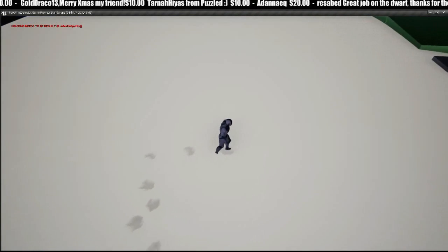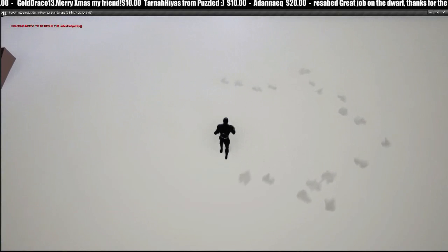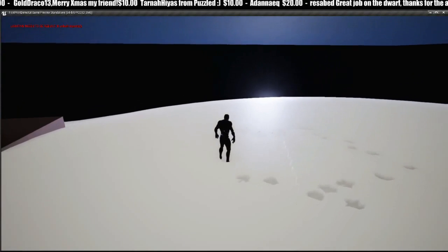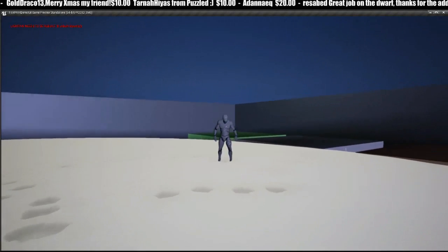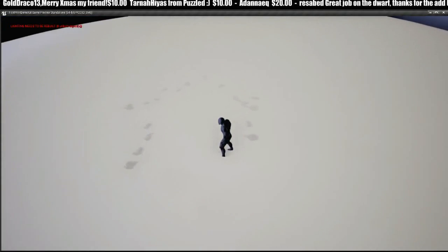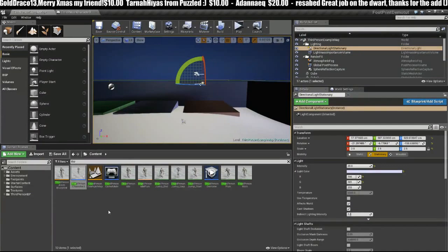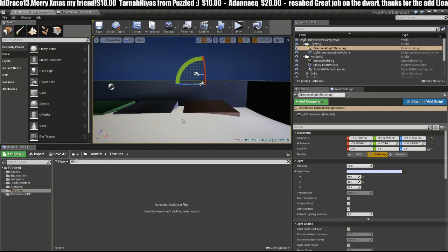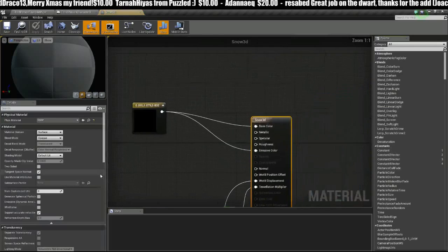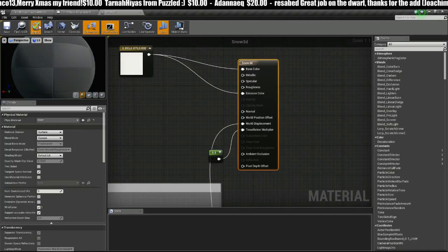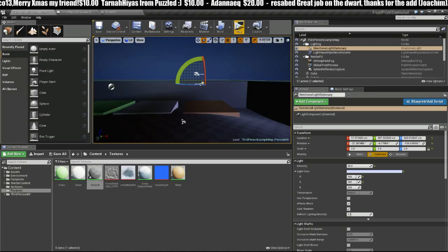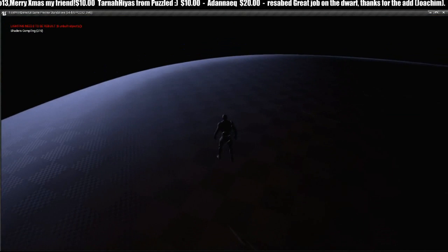Unfortunately now we can't see the decal as well. But there it's having a nice three-dimensional impact on the snow. And let me show you the tessellation that's going on. We can do that by jumping into our 3D snow texture, clicking on the output here, going down to wireframe, checking wireframe, applying, and letting those shaders compile.